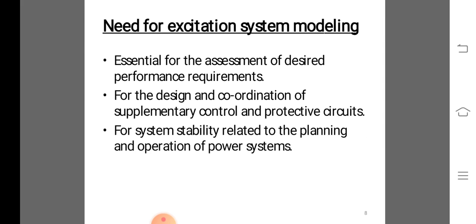Then the DC excitation system. The DC excitation system of this category utilizes a DC generator as the source of excitation power and provides current to the rotor of the synchronous machine through slip rings. The exciter may be driven by a motor or the shaft of the generator.